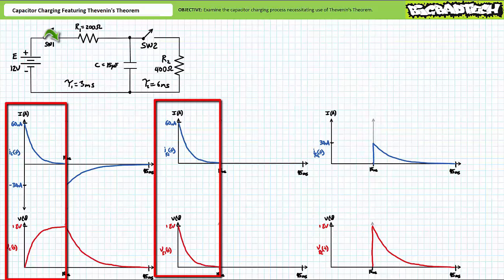While charging, we learned that current rushes through a resistor and into a capacitor. During the charge process, voltage across the capacitor rises. Current into the charging capacitor experiences an initial spike, which decays to zero after 5 time constants, at which time the capacitor is considered fully charged.